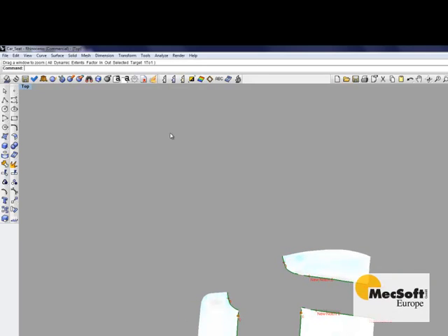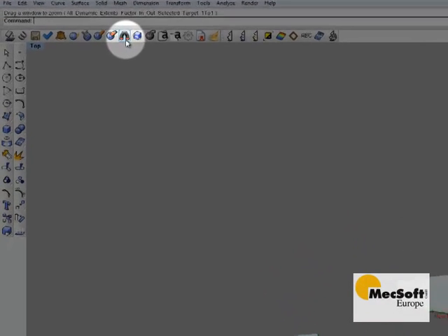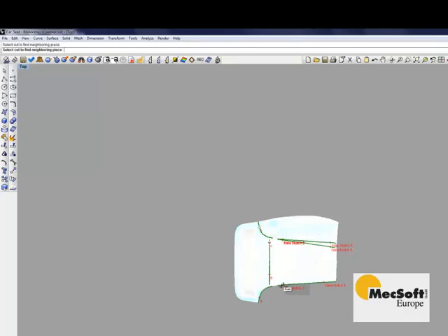Now I may want to go back and use the find tool again, and if I just click on a notch, it'll put these pieces back where they would go. So we have our piece now ready to export. We've added our seam allowance of 1/2 inch, and we've also added our notching information. So when they go back to sew these pieces together, we have notches that will allow the sewer to see exactly where all the pieces should go back together.